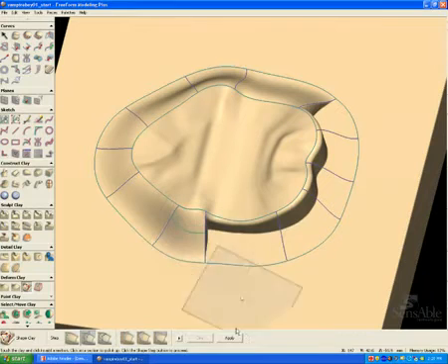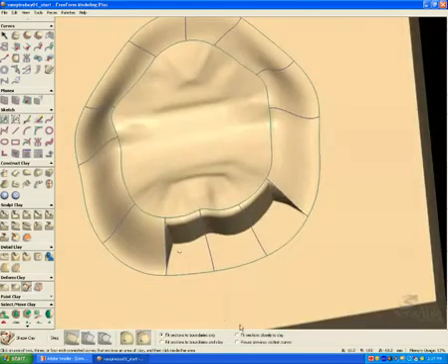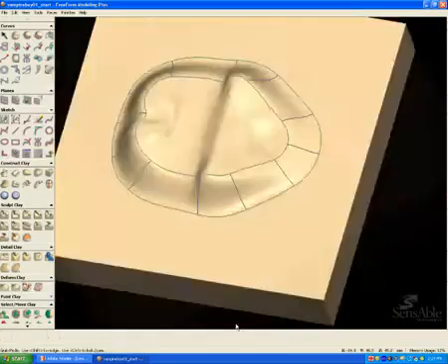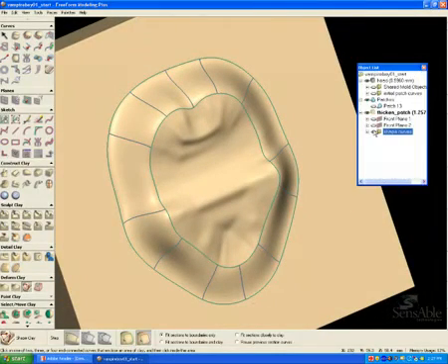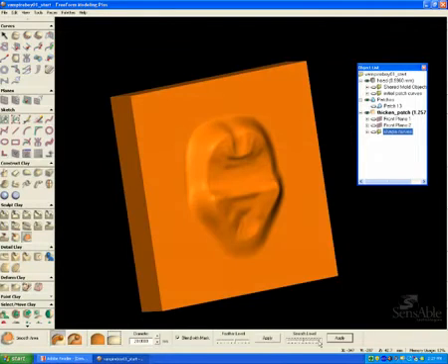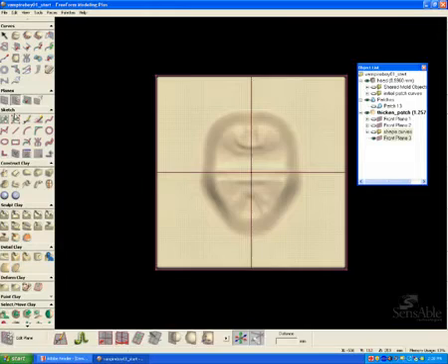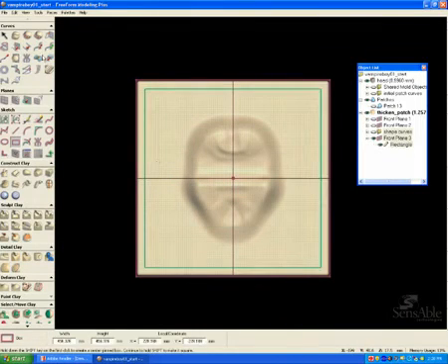The reason I'm doing this is because in the manufacturing process to create this complex parting surface, it will be a lot easier for a large ball cutter to simply mill this piece out with a more vague surface than to have that real sharp edge that you saw before. So now I have this much more complex, much more transitionary piece. I just smoothed it out real quick to make the transitions that much better.